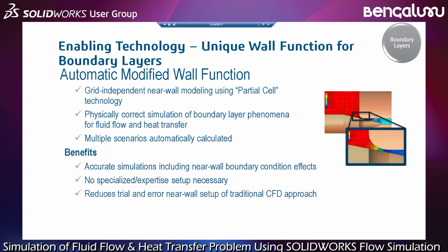Is there some roughness and so on? So it's very important to have accuracy on this because it drives the pressure drop, it drives the flow, it drives the velocity profile and so on. Okay, again, it is automatically modified by the software.